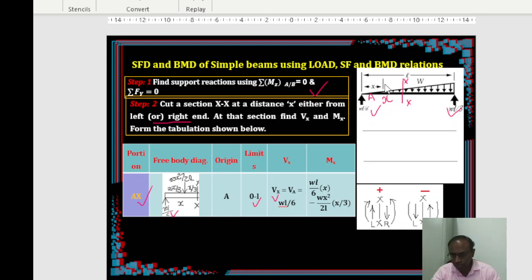Of course here it is x. Anyway, any section you can take, either this one or this one. So that section, if you have taken, the area of this diagram is nothing but your concentrated load. To get that you should know the load here first of all at the section. This comes from the simple similar triangles principle, or simply from the proportionate concept you can get it. At a distance L, load is W; at a distance x it becomes Wx by L.